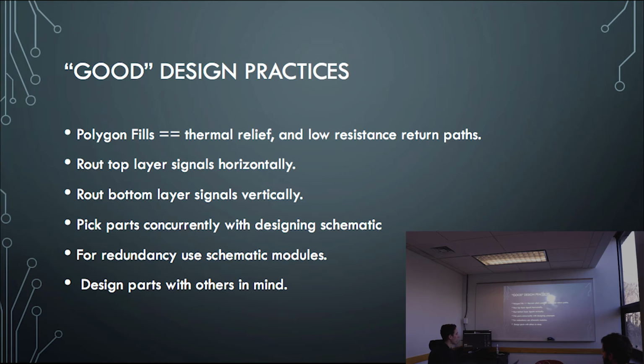So when I'm designing a board, I always know, unless special circumstances require, that big parts or high power parts, so usually switching power circuits or just any power application, are usually isolated away from the digital side. Really big if you're doing high power switching stuff, because that creates a lot of EM radiation that could affect, say, your Wi-Fi. So isolate your power.